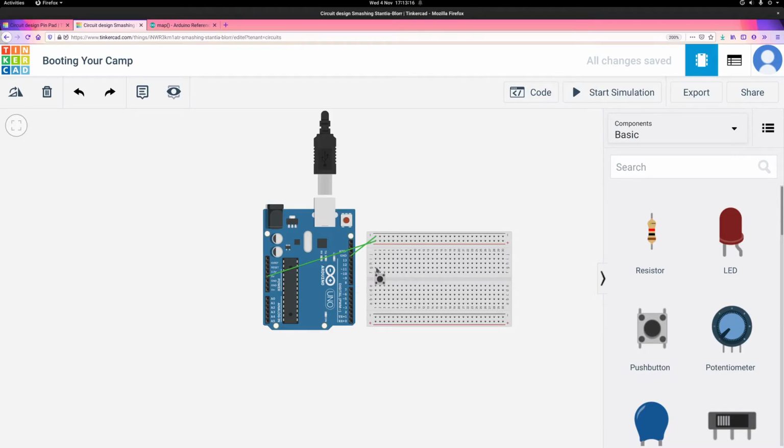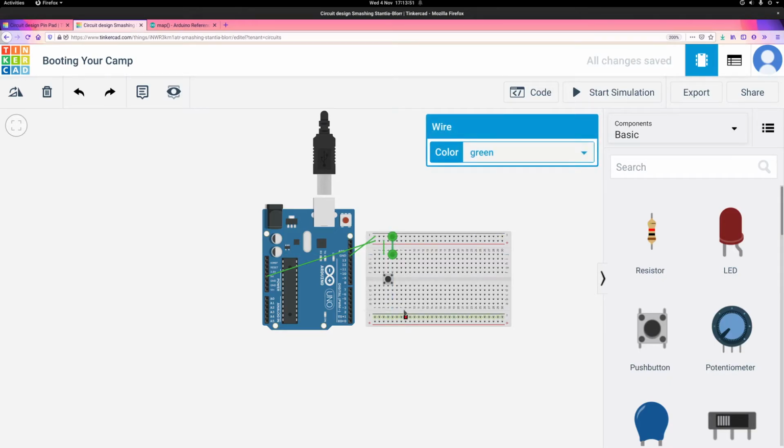So our button will put 5 volts on one side and 0 volts on the other, and then we can read between them. So our first step will be to take, and I'll slide this over a couple, power. We'll make that on this right side here. So this whole right side is a powered half of the button. And then this other half will be the negative half, and that'll be, say, the side that we read or something. Okay. Cool. So this whole side, yeah, we'll connect that to our negative.